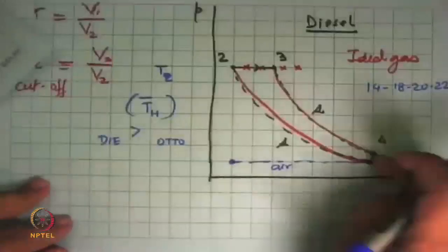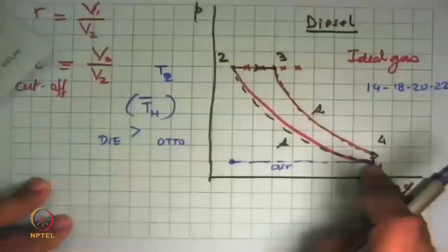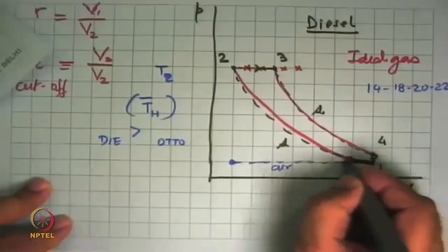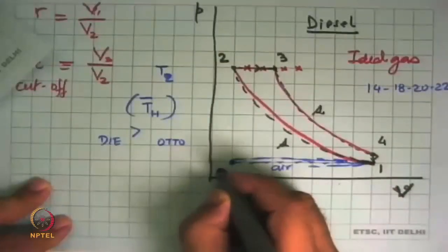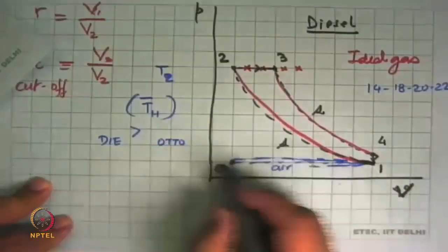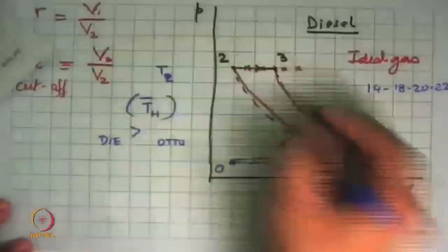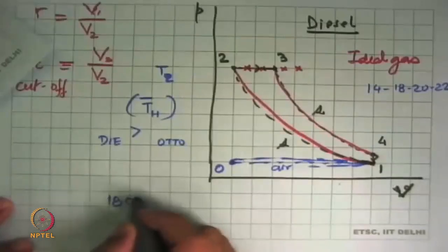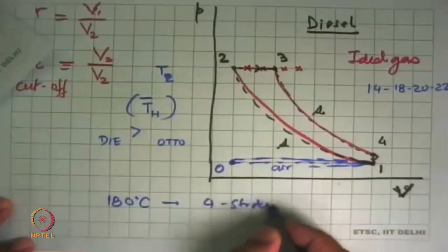To complete the real life treatment, air standard cycle is what we do here. The real cycle gets an additional thing. It takes in air, then compresses it, goes through it, and then it goes back over there and comes back to this state. So this we can call it zero state. Intake, outlet, there are two strokes. Then there is one stroke for compression and one is for power stroke. So each stroke is 180-degree rotation of the crankshaft. And so to take 4 strokes, you need 2 revolutions.